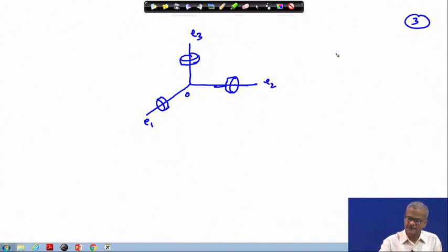So, in that case, the last term that we are writing, I w times omega spin times E a cap, if we have multiple wheels, we need to add for all of them. Say this is the ith wheel, its corresponding spin rate is omega I, and the corresponding E a direction is E a I. So, you sum it over 1 to 3 if you have 3 wheels.